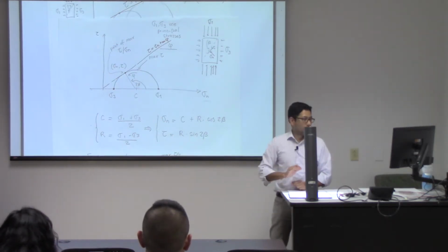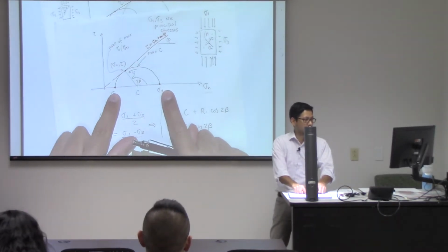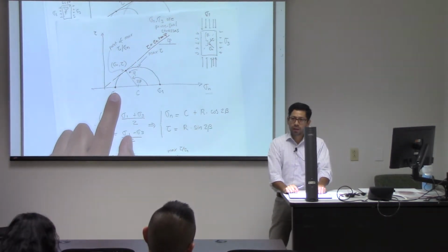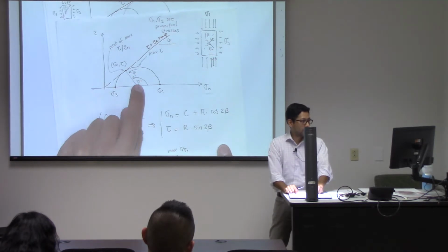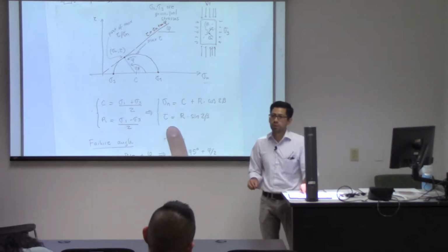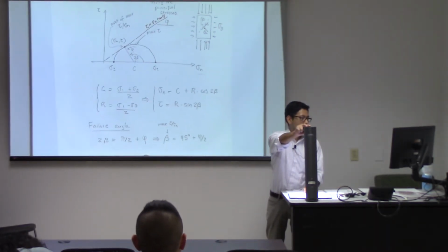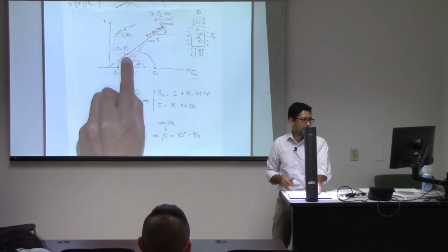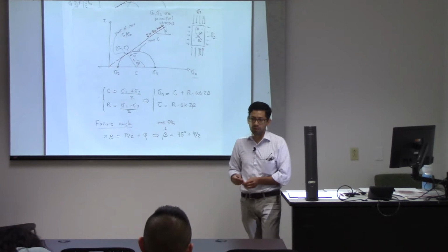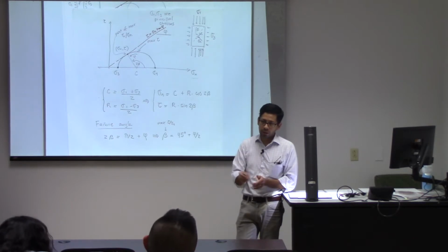So this is all you need to know about the Mohr circle. How do you draw a Mohr circle? You find the principal stresses, you draw those on the x-axis, you draw a circle in the middle, and that's it. And then you have to know how to compute the stresses at a given orientation. We're going to do a lot more of this when we talk about faults. But for now, I'd like you to just remember what a failure angle is and why it is located there. It's related to the failure line that we have drawn there, which depends on the frictional strength of the rock.